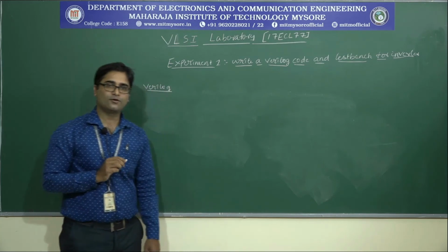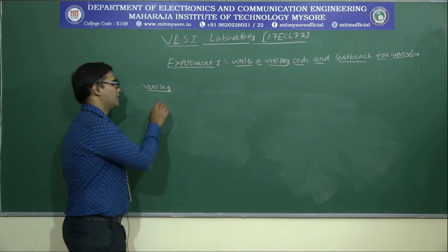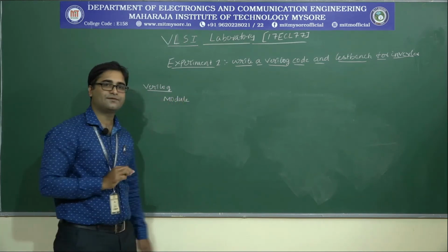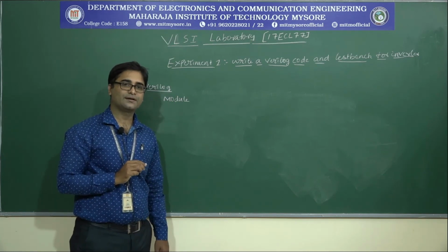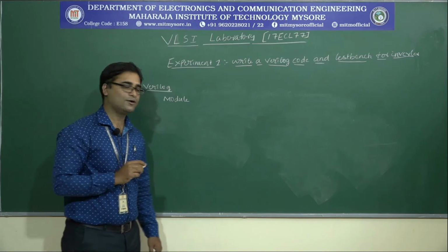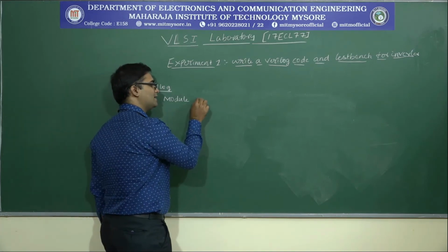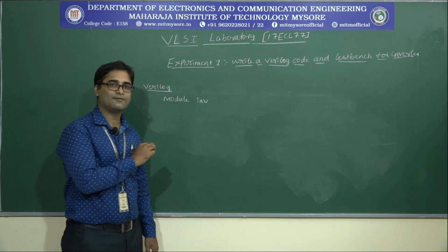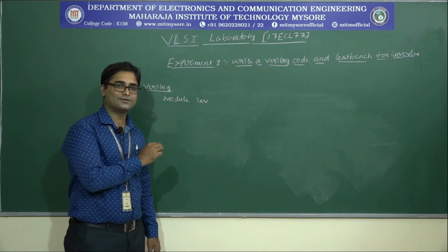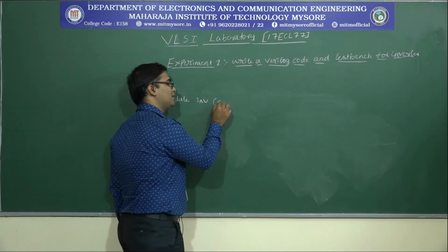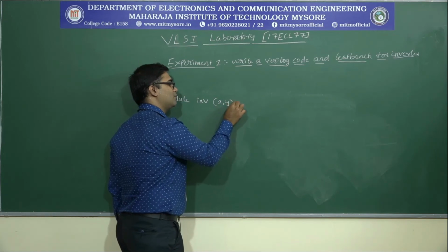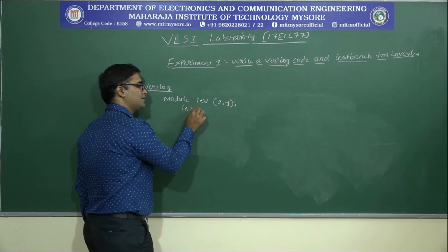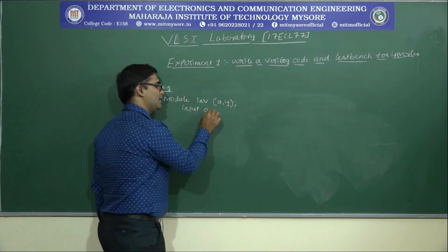So for writing the Verilog code for the particular inverter, it starts with module, which defines the functionality that we are writing the code in Verilog, followed by the name. Let us define it as INV, followed by the ports list, as we have seen in the circuit where we have defined the input as A and the output as Y. Next we will define the port declaration, an input of A,